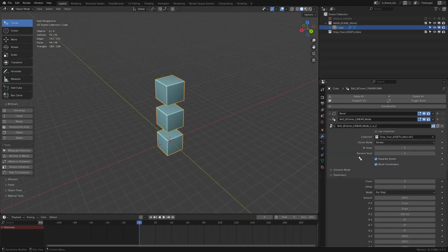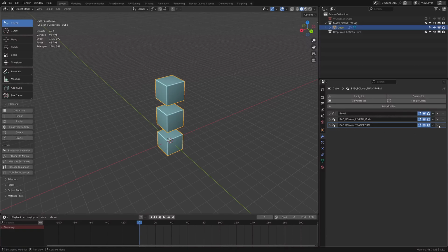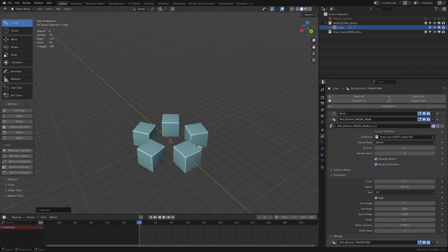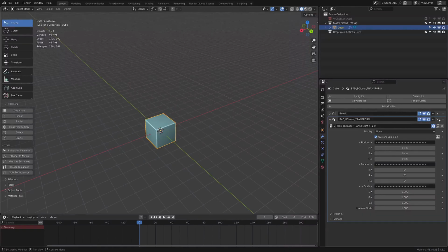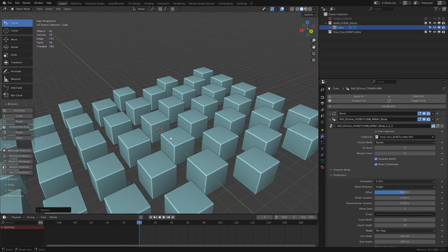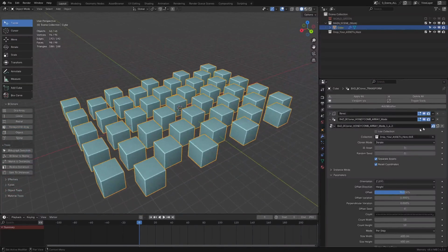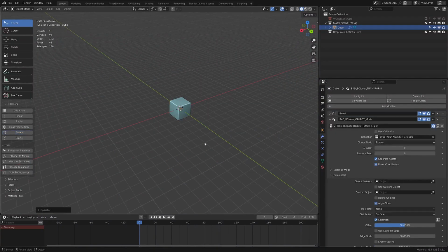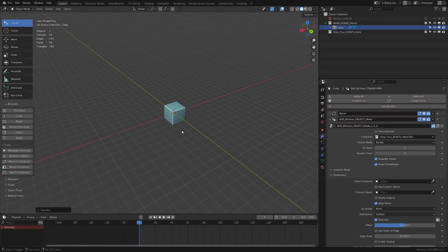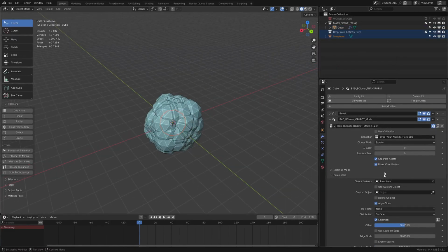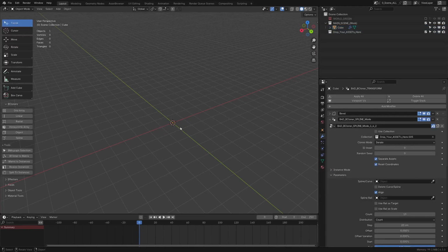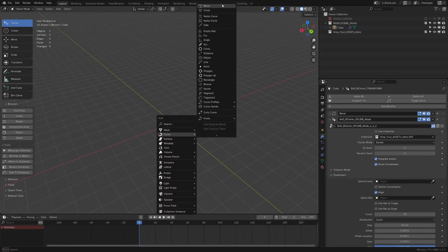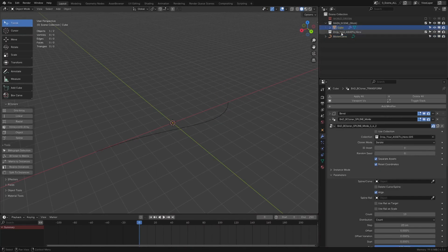BCloner linear, with this tool, you can create a line or diagonal with any number of instances. BCloner radial, with this, you can create circular, radial, or spiral instances. BCloner honeycomb, this tool allows you to create a honeycomb grid of instances. BCloner object, this tool allows you to generate instances based on the vertex, surface, edges, or volume of any mesh object. BCloner spline, this last generator needs any spline, and you can generate any number of instances along that spline.